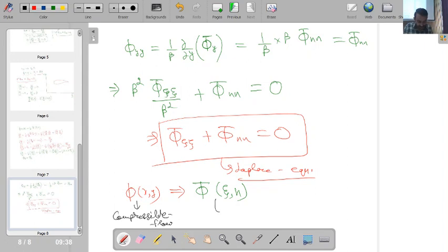So in the zeta eta plane this flow has become incompressible. Now we know that incompressible flow is easy to analyze. So whatever parameters I have analyzed in the zeta eta plane, these can be then mapped back to the compressible flow plane.